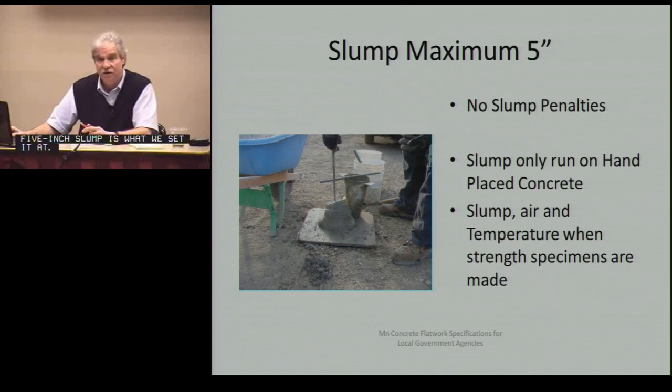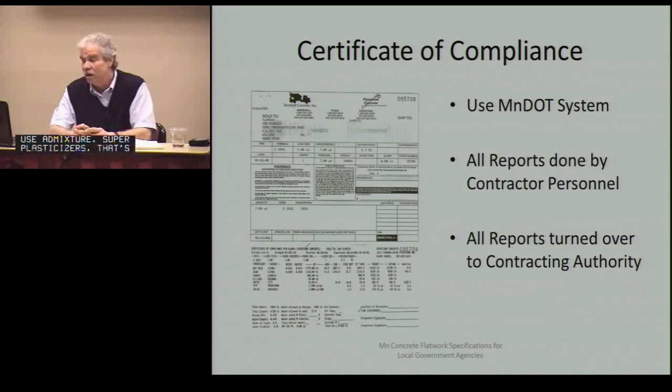That's between the contractor and the ready-mix supplier. So that's where the mix is really their mix. We want the certificate of compliance reports that the MnDOT system developed and the ready-mix people have invested in to be used on this project. We use the same system MnDOT does, and one of these comes with every truck that's delivered.